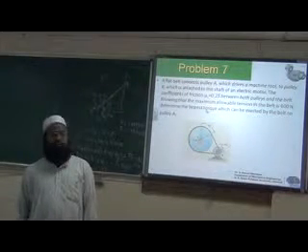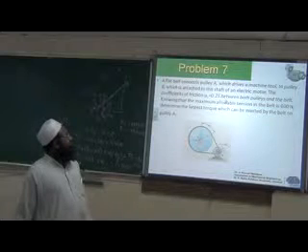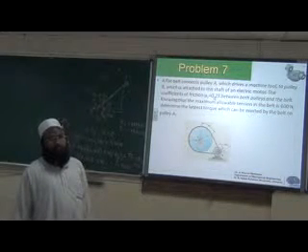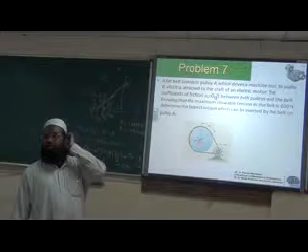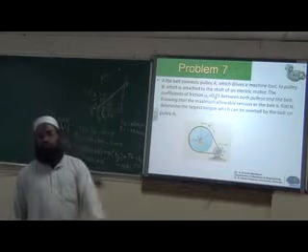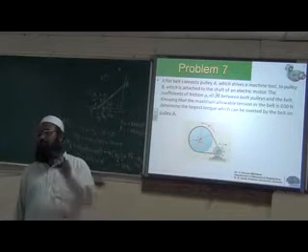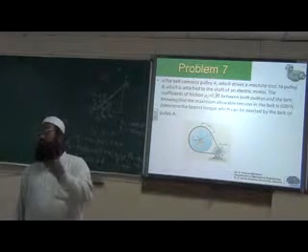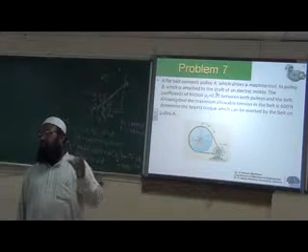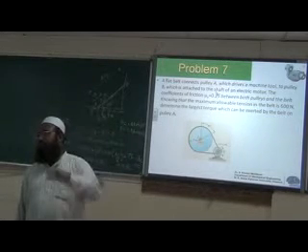So we can apply the T1 by T2 equation, find out the two tensions first. One tension is given, the other tension you have to find out. So in order to use that equation, we should know theta, angle of lap, and mu is given. Okay, so we should know angle of lap.